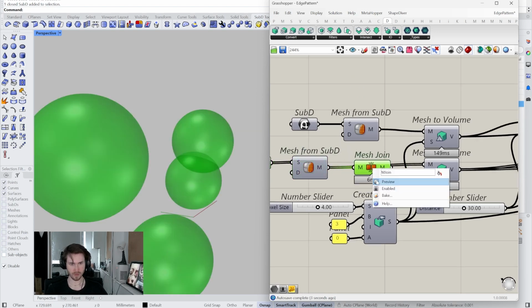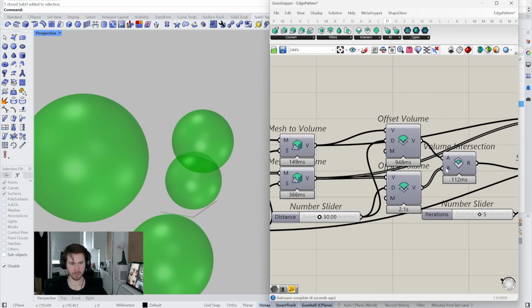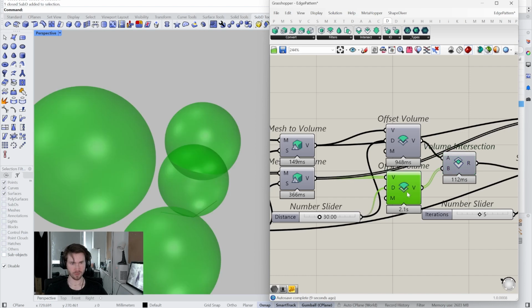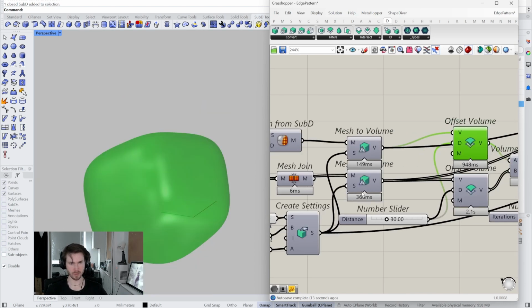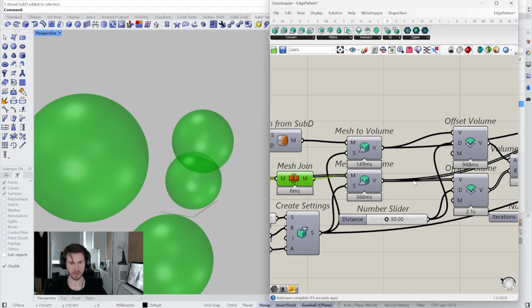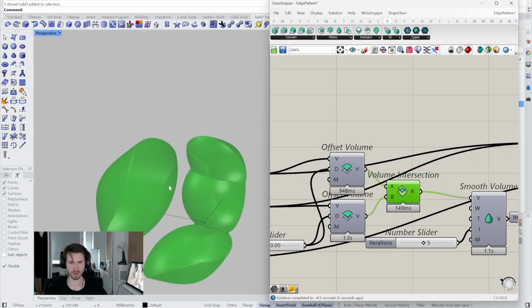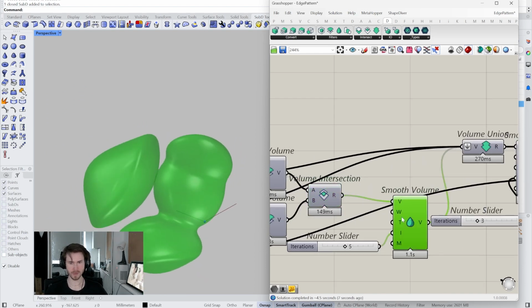So now these are all a single mesh, because right here with the intersection we're getting a bad result just because we have 4 separate volumes here compared to this one for the box. So if we have them all together as a single mesh, that should solve that, because then it'll give us only one volume for all the spheres. So one volume there, do the intersection, get a much better result.